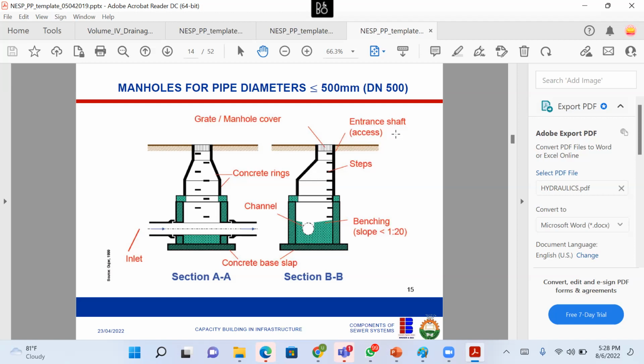So does this apply also to domestic sewer lines or just for roads? Most domestic sewer lines. Well, this is a domestic sewer line we're talking about. You can see the pipe size is very small. But the same principle applies to the other one. Okay, so it should be a minimum of 1.5 from the surface. No, I said between 1.2. There are other things that affect that.